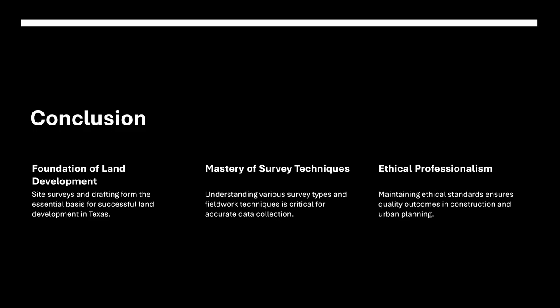Finally, we return to comparisons. Boundary surveys look backwards. Site surveys look forward. Plats formalize conditions into legal records. ALTA surveys combine them all into one comprehensive standard. Construction staking bridges site surveys into the world of construction. And as a drafter, you must be able to navigate all of these phases, understanding the difference, but applying the same professional discipline to each one.